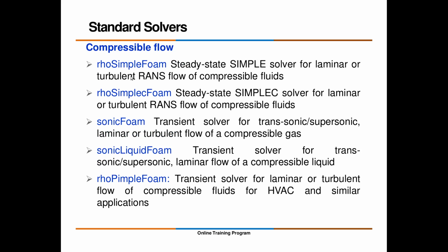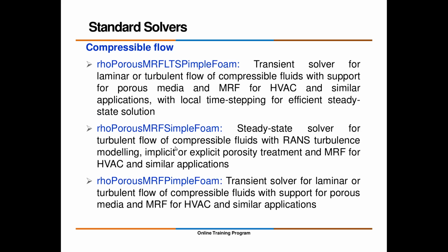For compressible, rhoSimpleFoam is a steady state solver for laminar or turbulent flow of a compressible fluid. rhoSimpleFoam has a corrector in the SIMPLE algorithm, so that class of solver is available. sonicFoam, sonicLiquidFoam, and rhoPimpleFoam for different classes of applications are available. rhoPorousMRFLTSPimpleFoam is for MRF and HVAC applications. rhoPorousMRFSimpleFoam runs steady state for HVAC applications. This one is transient. Please understand, wherever you see simple, it is steady state. Wherever you see pimple or piso, it is transient. It's very simple.